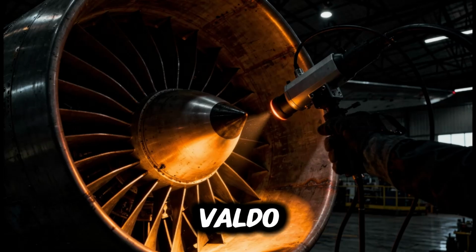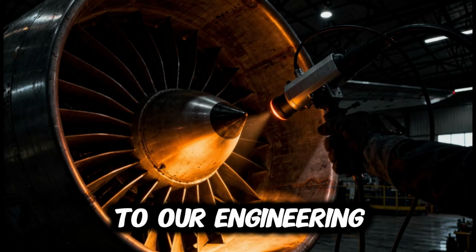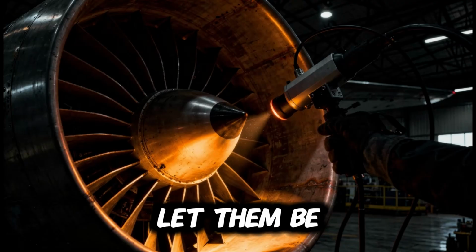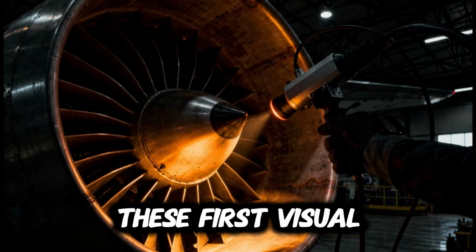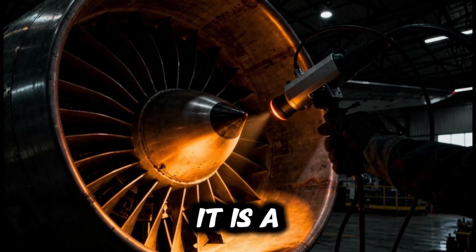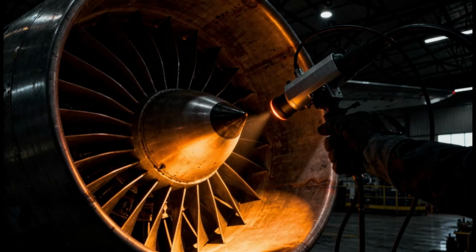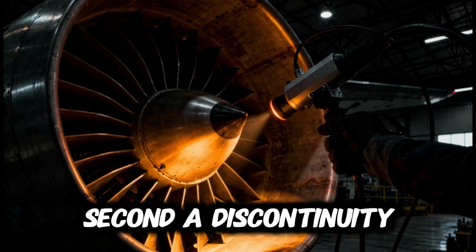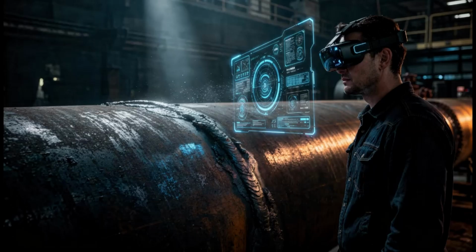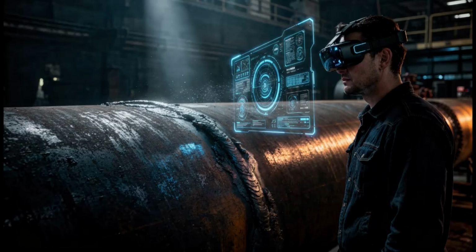Thank you, Ivanivaldo, for walking us through the complete architecture of visual testing. To our engineering students listening, if you take away 3 things from this episode, let them be these. First, visual testing is never just looking. It is a controlled interaction of light, physiology, and procedure. Second, a discontinuity is not a defect until it crosses a documented acceptance limit. Your job is to know that limit before you inspect.